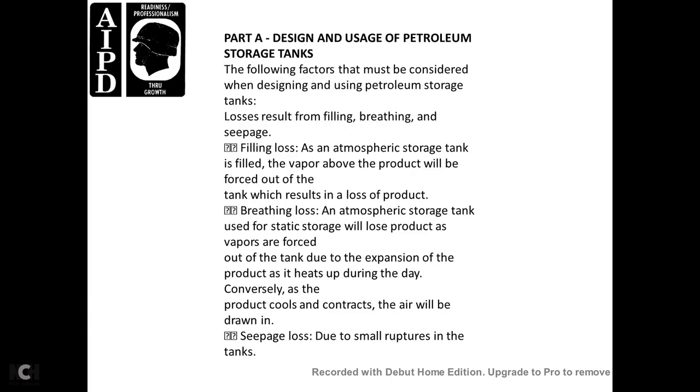Part A, designing and using a petroleum storage tank. The following factors must be considered when designing and using petroleum storage tanks. Losses result from filling, breathing, and seepage. Filling loss: when an atmospheric storage tank is filled, the vapor above the product will be forced out of the tank, with the result of loss of the product.